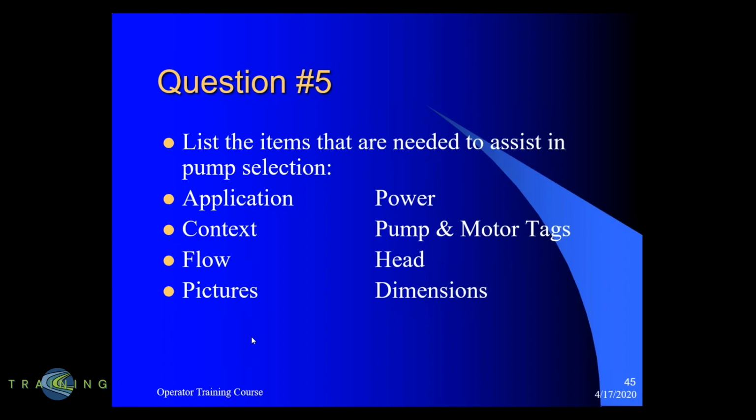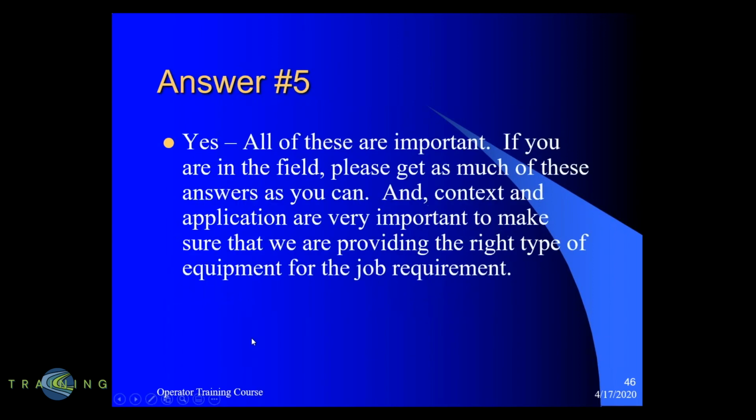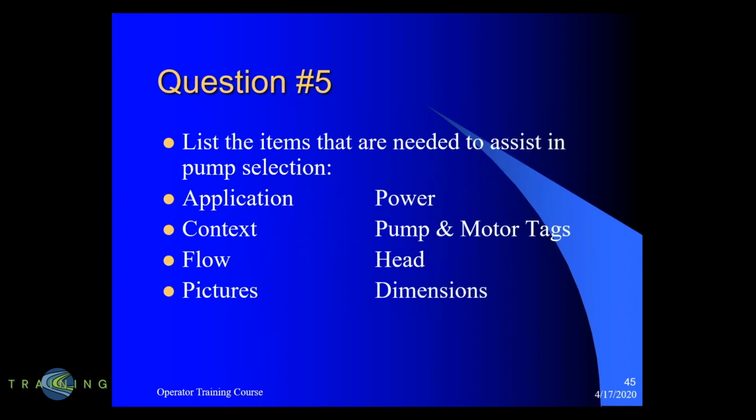Pictures and dimensions. When we're trying to fit something back into an existing application, seeing how we have to make modifications to the plumbing, checking about how the lay lengths are going to fit, very important. So the answer to this one is yes, please get all of this information to help us in selecting a pump to replace something that's out in the field that's existing.